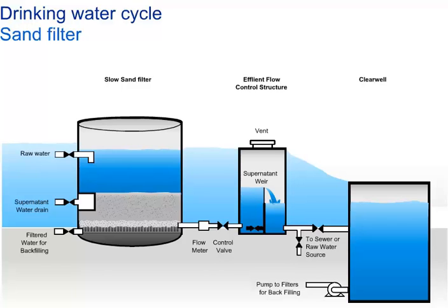The most common type of filter is a rapid sand filter. Water moves vertically through sand, which often has a layer of activated carbon above the sand. The top layer removes organic compounds, which contribute to taste and odor. The space between sand particles is larger than the smallest suspended particles, so simple filtration is not enough. Most particles pass through surface layers but are trapped in pore spaces or adhere to sand particles.